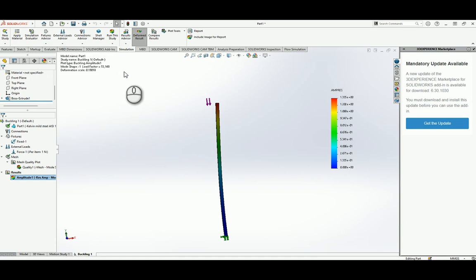So that is how we do a basic buckling analysis and determine critical buckling loads in SolidWorks. Now this would be a pre-analysis. Remember we spoke about pre-analysis. You would do a basic system first like this and verify it with your hand calculations, and we can tell that SolidWorks is giving us a reasonable value and calculating our buckling loads as we expect.